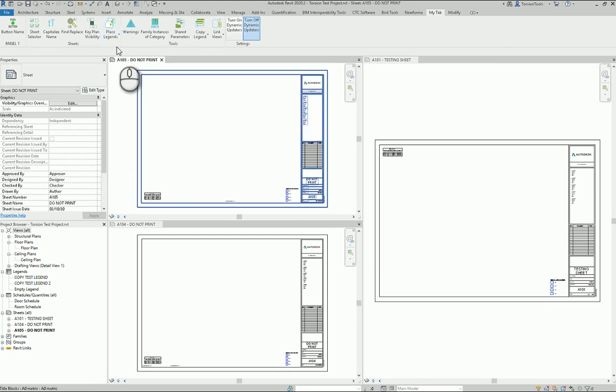Again, there's a lot of functionality that actually is going on behind the scenes that makes some of these things work. We're finally using the sheet selection method, the shared parameters, looking at external files, external definitions, how to pull and push information in and out, create shared files, shared parameters within the families. We're using dynamic updaters now to do things on the fly, so like naming sheets. There's also ways to do that so you can catch views. So when views are made, you can also name views. You can add information to views, title on sheet. There's just a wide range of things that can happen once you start using dynamic updaters.